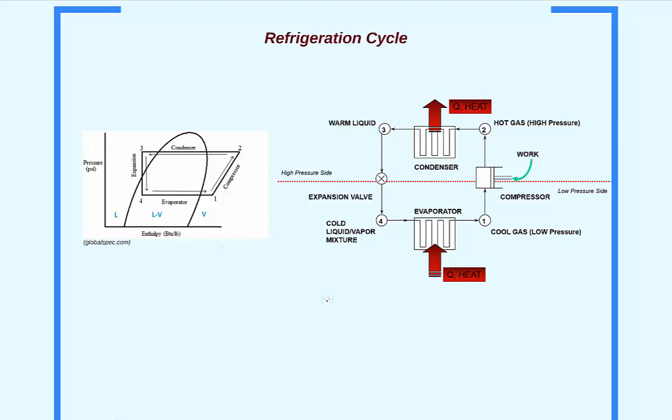When the refrigerant leaves the evaporator, it is now 100% vapor. It is important that the refrigerant leaving the evaporator is indeed 100% vapor. This prevents liquid from entering the compressor. Since liquid is an incompressible fluid, flooding the compressor runs the risk of damaging this expensive component.